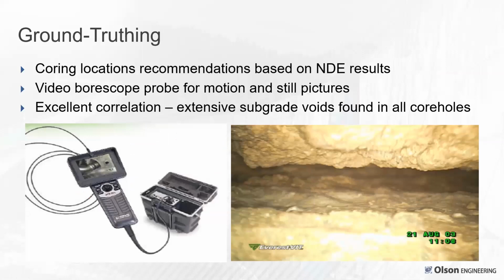So we did take the cores, and we had a borescope that was a very sophisticated one. You can actually drive it with a joystick, so we could go in a hole and take pictures below the slab. And we confirmed they were voids, and it could go out about 10 feet from a given core hole location to see conditions. So a successful project, and they were able to recommend the slab grouting type repairs to restore the spillway support.